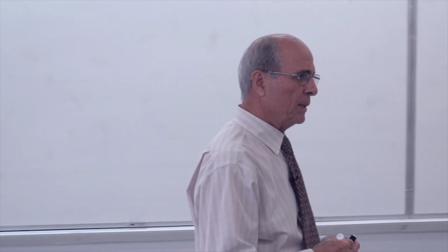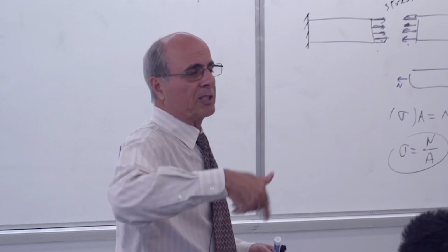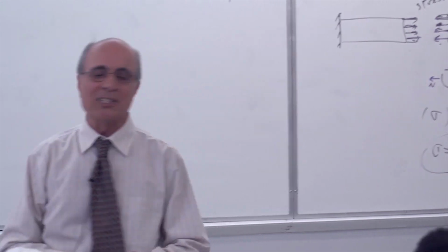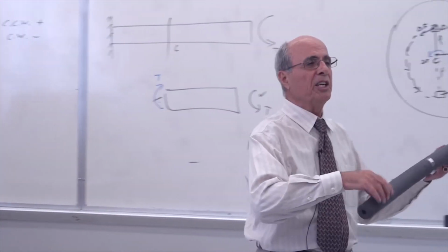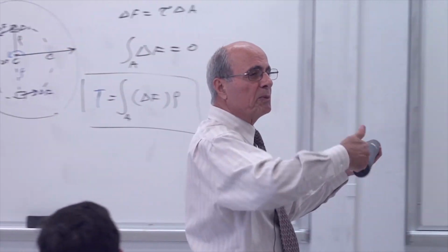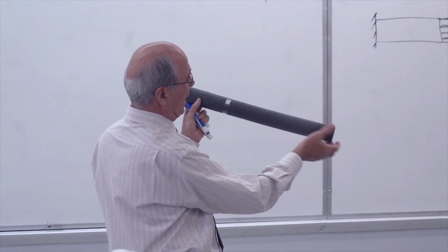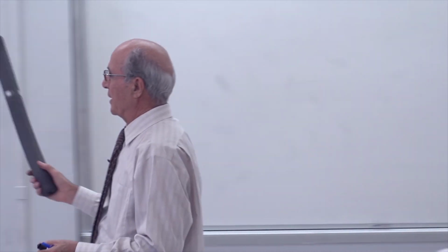What's the question? Oh, is the stress in the middle 0 because it's not actually loaded? If it were loaded, no, that doesn't matter, because the stress is 0 because it doesn't turn. You see, it doesn't turn. Because we'll get the formula in a minute. You will see that. Because here, when you turn it around, the outside will shift, but the center stays at the center. Look, this line, the more outside you go, the more rotation you have. So therefore, that is the case.